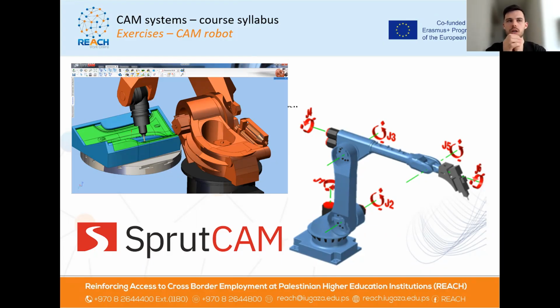And they're also learning what is the best way to clamp the workpiece material so that it will stay there, and what is the best way to clamp the tool, and how this length of the tool is then transferred into the program, so that the program knows that your tool is 10 millimeters long or 100 millimeters long and not 150 millimeters long.